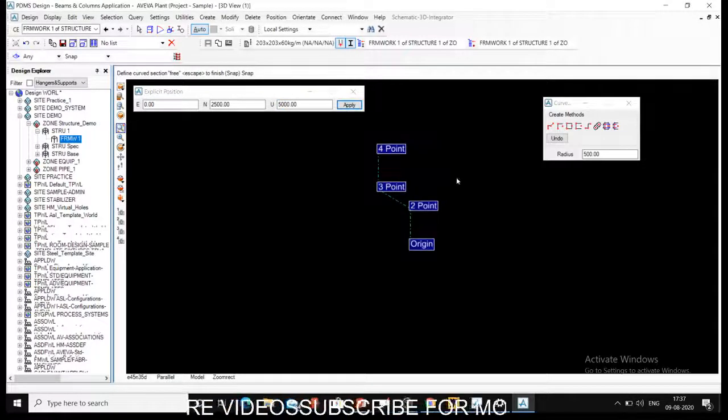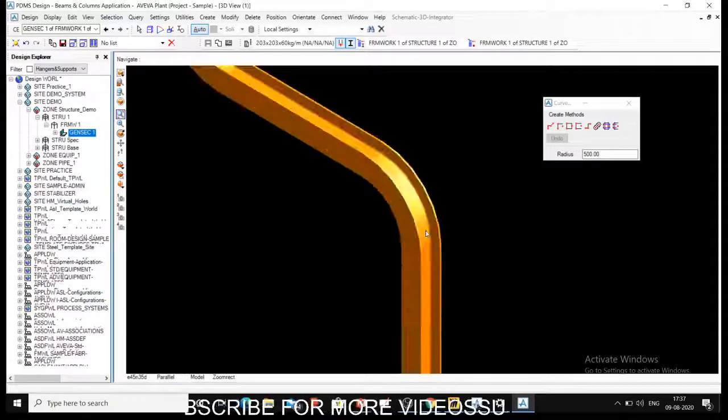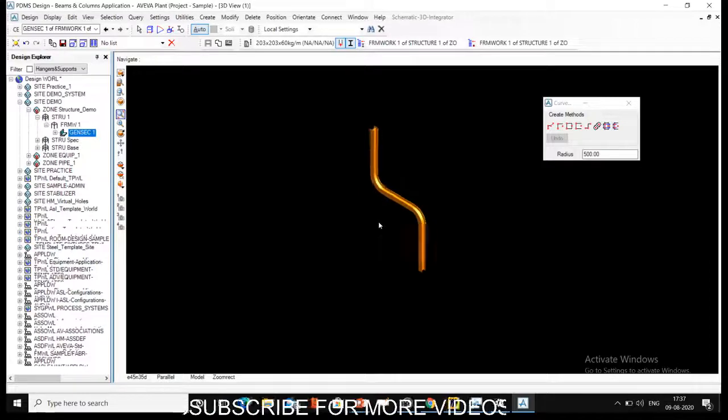Okay, so we have 3 points here. Just press escape and the section will be created. So this is basically a curved section. This radius is whatever radius we are putting. Right now it is 500, so there will be two radii at each point. This is the free type of curved section.